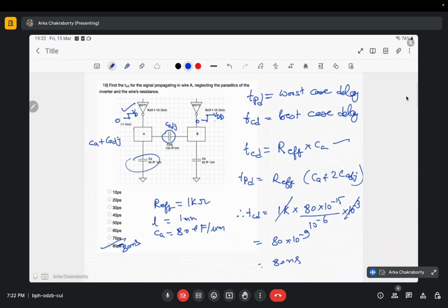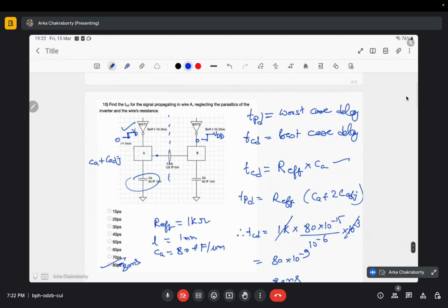direction, the circuit is completely symmetric, right-hand side and left-hand side. So the voltage that would be developed here, say Vx, due to this changing voltage, and the voltage that would be developed here, say Vy, would be similar. As the voltage developed across these two terminals is similar, the voltage difference Vxy would be 0. It is more appropriate to say V adjacent, the voltage across this C adjacent, would be Vx minus Vy, which equals 0.